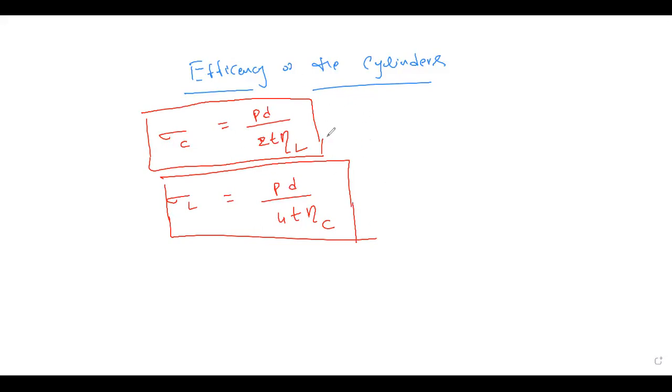Yeah, so I think almost we have covered all the formulas in thin cylinders. And one more important formula, your volumetric strain. So if you want to calculate volumetric strain directly, you can use this formula, which is an algebraic sum of net strains in all the axes. So volumetric strain will be a summation of